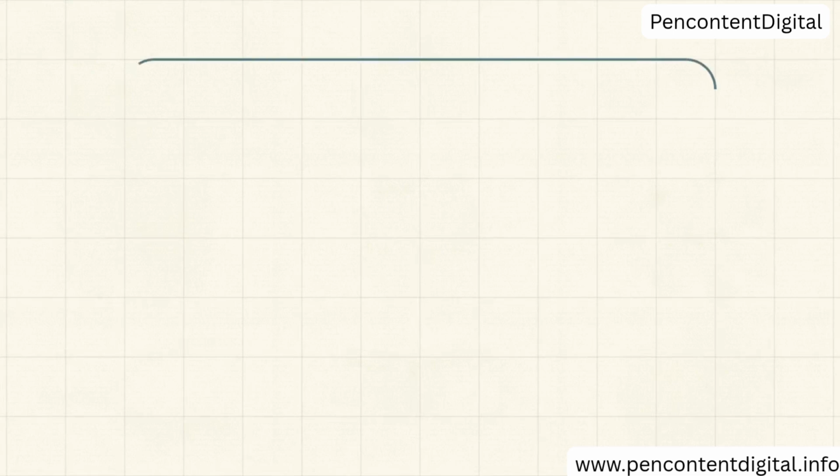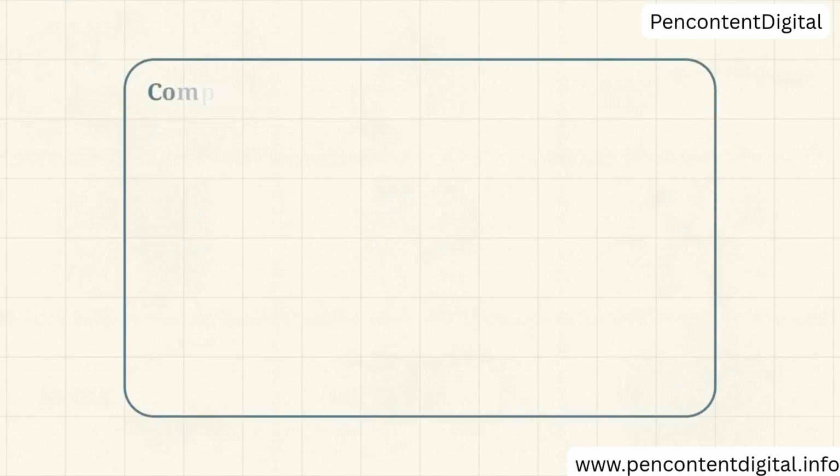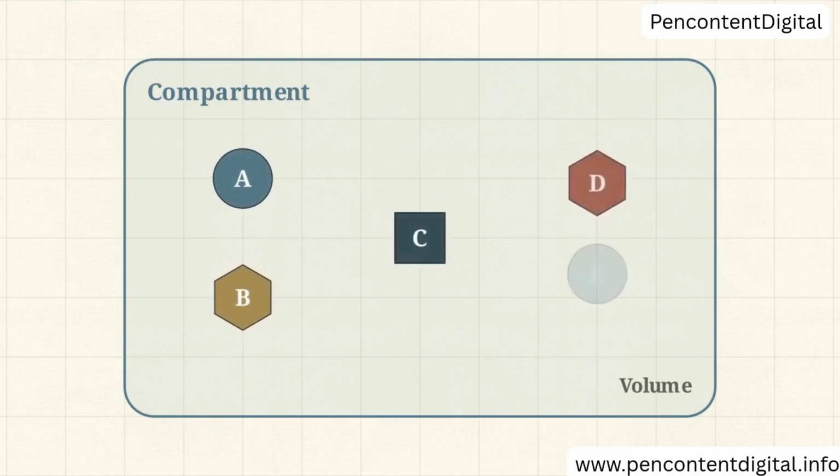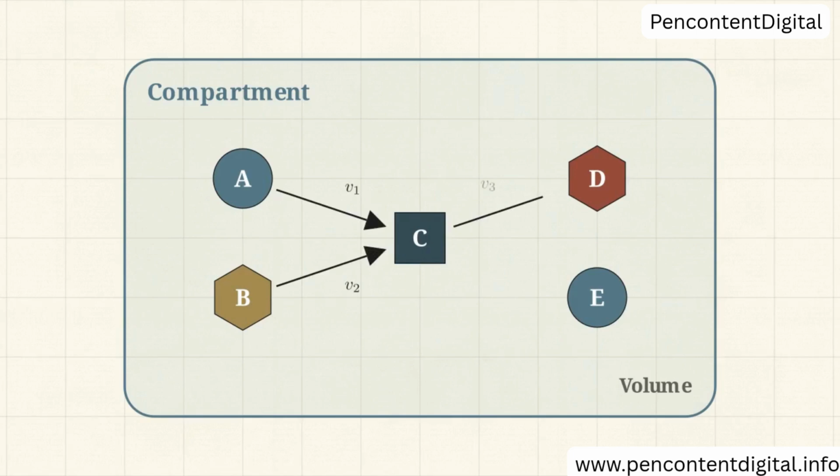The process begins here in a blank grid space. The first step is drawing a physical boundary box, which COPASI defines as a compartment. Without defining this physical volume, it is impossible to calculate accurate molecular concentrations. The physical space dictates the biological rules. Next, we populate that space. We introduce distinct molecular species, representing specific proteins or metabolites, directly into the compartment.